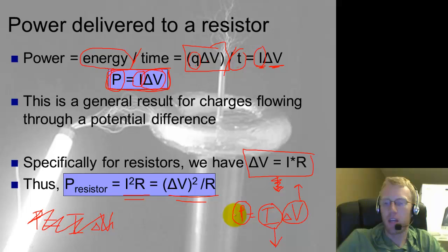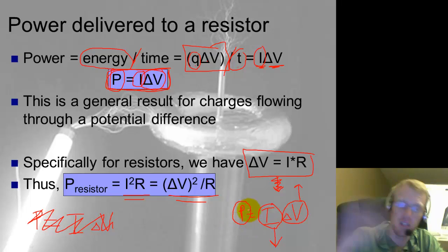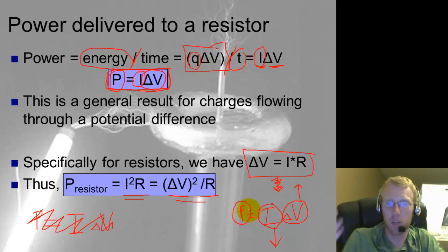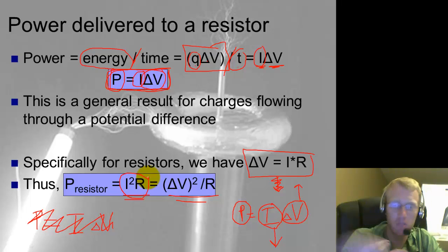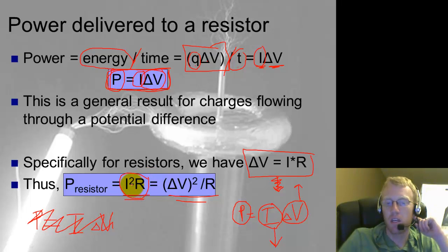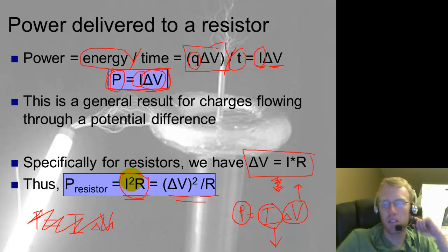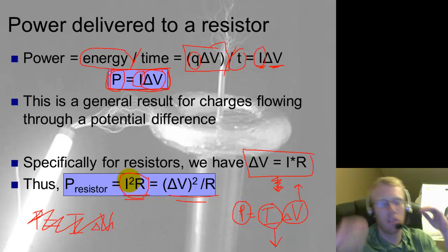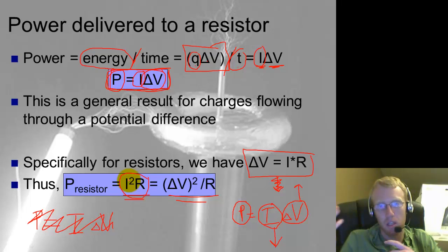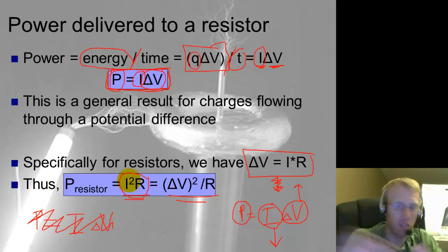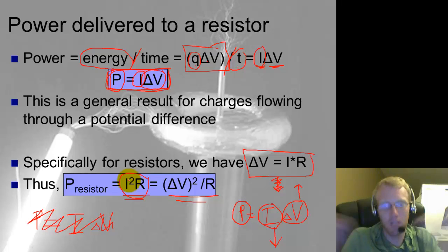And so while the total power delivered to your house, say, for example, is going to be the same, the power lost due to the resistance in the wires themselves will decrease because the current is being decreased. So there's two types of power that you can kind of think about. The power delivered, which is current times voltage coming into your house, for example. Then there's also the power lost in the wires themselves, because all wires have a little bit of resistance.